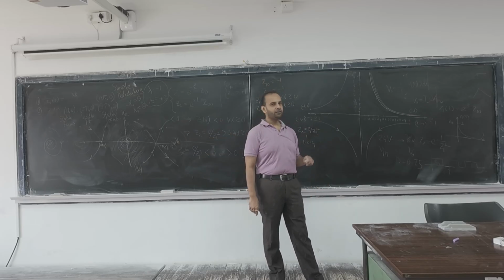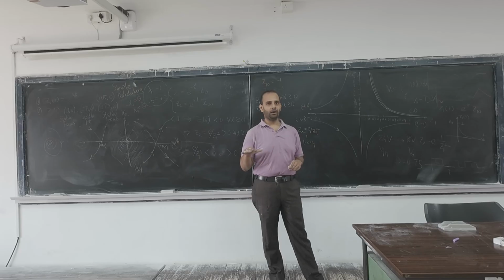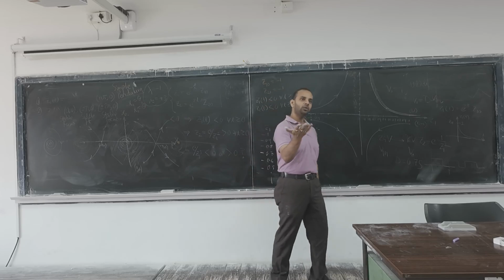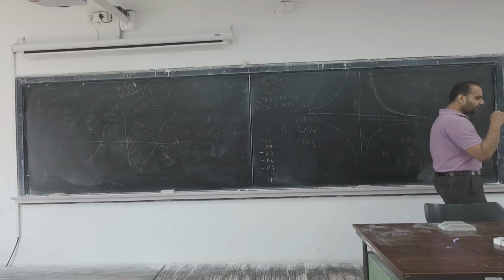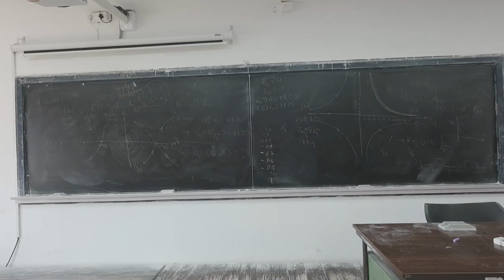Here this buck converter means it's a DC-DC chopper. You heard about a transformer stepping up or stepping down voltage. So this chopper is analogous to a DC transformer, because a transformer doesn't work with DC, so we use semiconductor devices or power electronic devices for stepping up or stepping down a DC voltage. So here, from 24, we are reducing the voltage. That's why it is called a step down chopper, whose technical name is a buck converter.